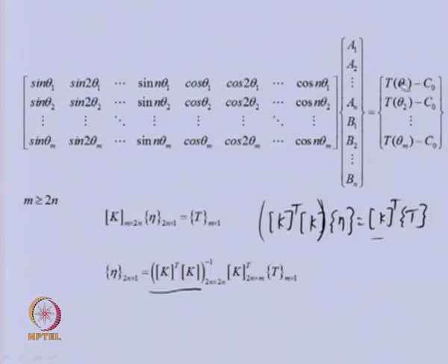You can see that the torque we have expressed in terms of sine and cosine and their higher harmonics. So, obviously, while designing, these frequencies and the natural frequency of the system should not coincide, otherwise we will have a torsional resonance condition.